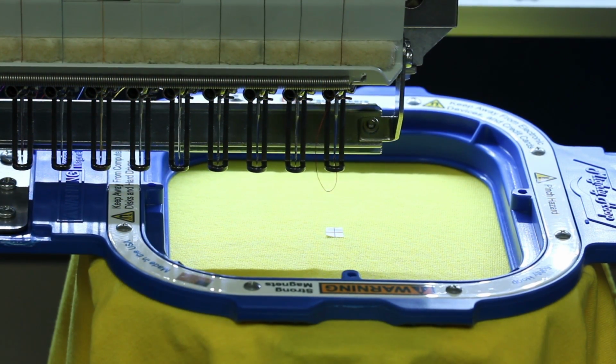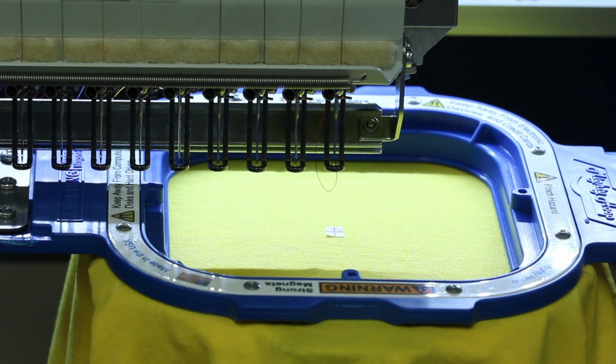I always need to make sure that my needle is not going to hit the hoop. And a huge rule of thumb is that you always want to choose the correct hoop for your design. If you do hit a hoop, this can be very unfortunate and it can cause major problems within the inside of the machine. No matter what machine you have, you always want to trace no matter what before stitching.